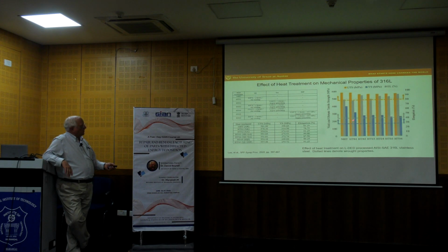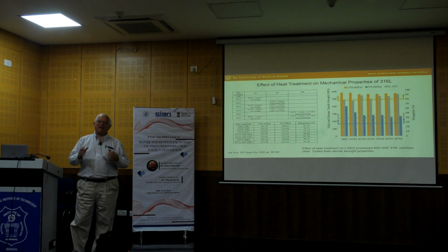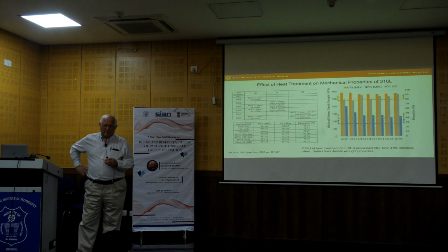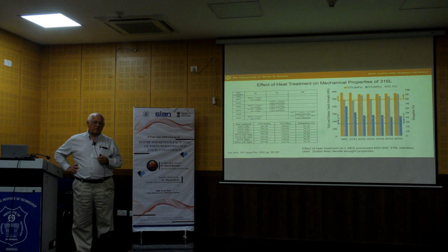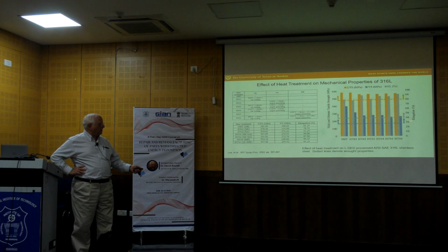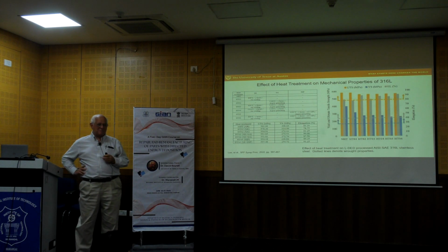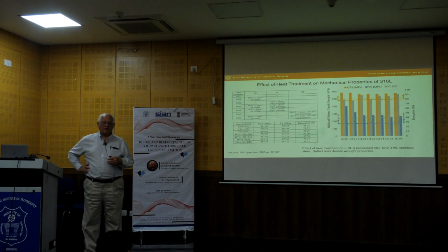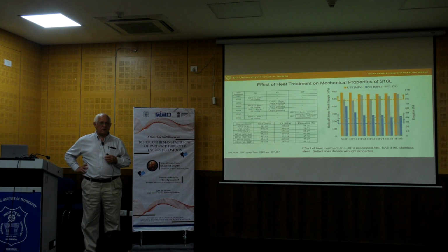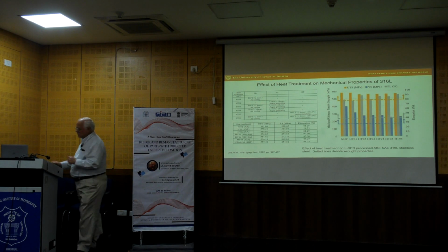The impact of the yield strength going down, the tensile strength staying high, and the ductility staying fairly uniform is that as we do the heat treatments over here, the material is becoming more work hardenable, which means that the work hardening exponent is increasing, which typically is a good thing. So we like that. But anyway, that's the way stainless works with DED.